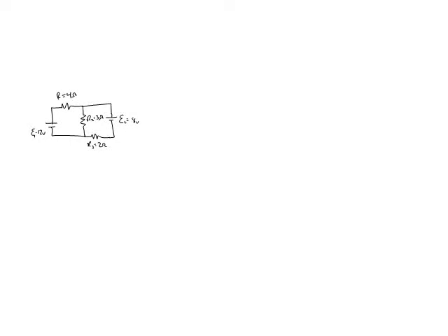Okay, so the first thing you want to do is designate your current. Now, you start with the battery. So this is a little one and that's a big one. So the current is going to be I1, and that'll take care of anything on this line. And this one is going to go that way, so we'll call that I2. They're going to come together right here, and they're going to be forced down this way. This will be I3. So I1, I2. That will leave us with our first rule, the junction rule, which is the easiest one: I3 should be made up of I1 and I2.